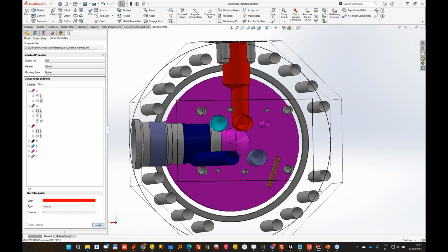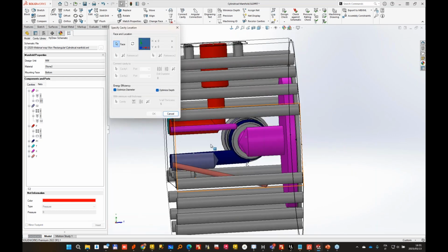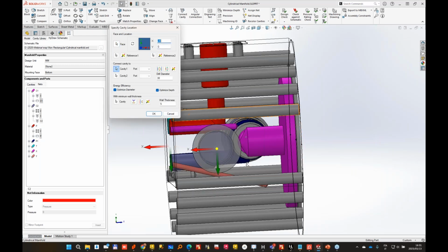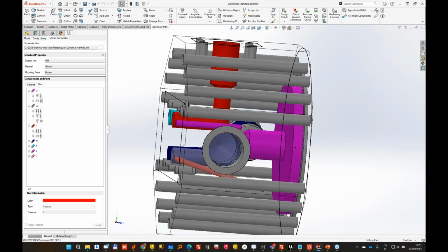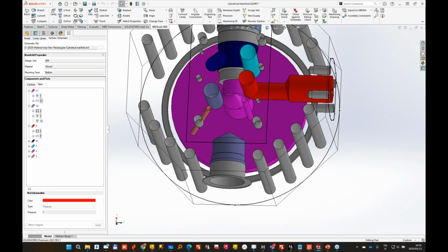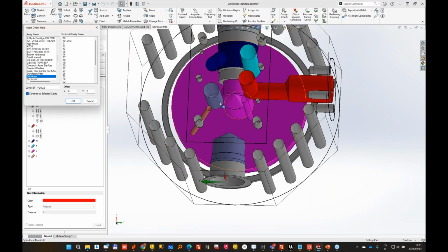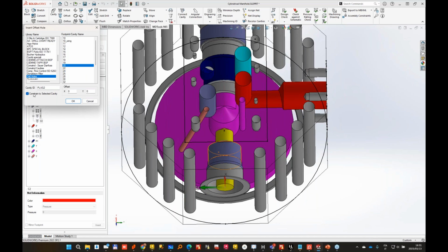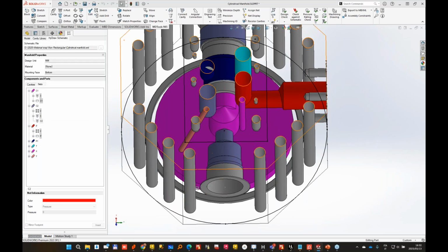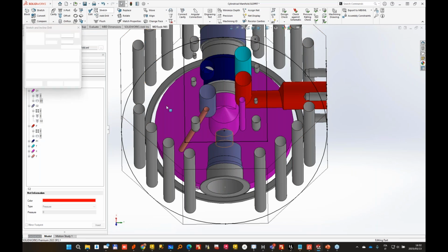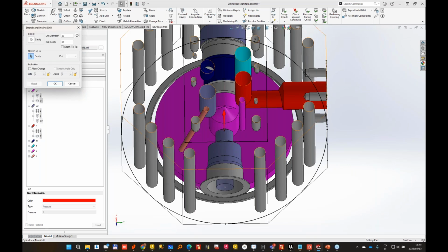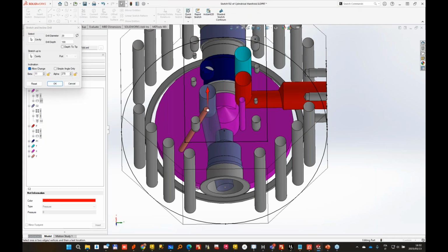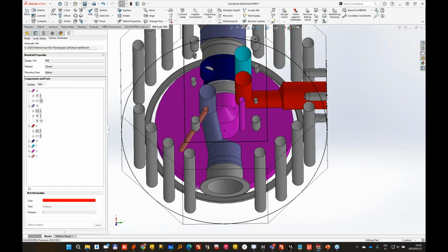So I'll take my C2 and put it somewhere here. Again, in the center, maybe minus 50. And I'll use the same technique, so I will do an offset hole again here. I don't want to incline the entire port. I will just make inclined drills. And I can stretch this with inclination. And I can save my block.